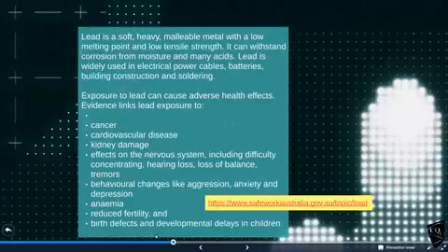It can't be used as a vertical cladding because it creeps under its own weight and normal heat, so it slowly creeps. But on a low-pitched roof, it's good. You can make ornate water goods, top of a rainwater pipe. You can put a lovely hopper on the top of it.